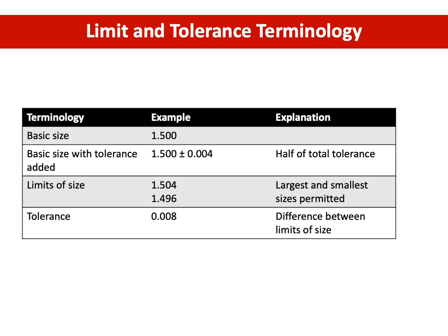Here you can see the terminology of tolerance. If you refer back to the last slide, the size you have is 1.500, and it is given as 1.50 plus minus 0.04. This is the basic size plus a tolerance added.